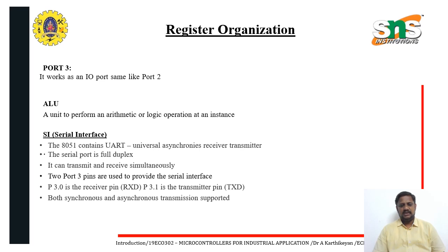The port 3 pins are used to provide the serial interface. P3.0 is the receiver, that is RXD, and P3.1 is the transmitter, that is TXD. So pin 3.0 is the receiver pin and P3.1 is the transmitter pin. Both synchronous and asynchronous transmission are supported, mainly through port 3.